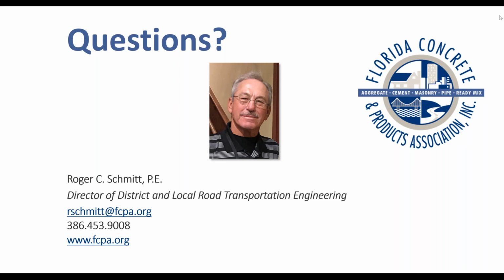So if it isn't tied, then I would say that you really can't consider that as edge support. But a lot of folks, like for parking lots and for some residential streets, their curb and gutter will be poured in conjunction with the lane. So it's an integrated curb and gutter, and that would be considered edge support then.